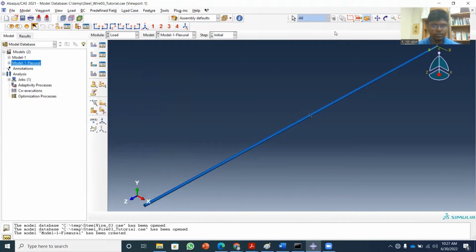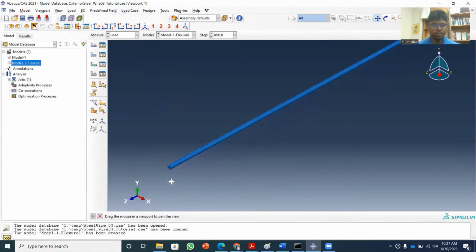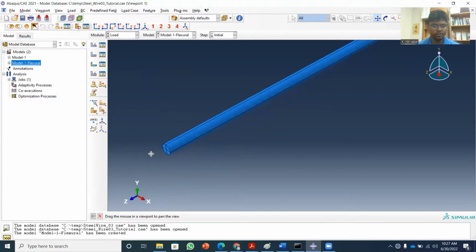While we were generating the longitudinal mode, we were applying our tone burst, or the load, on this surface, so the longitudinal, or in the axis of the pipe. Okay, but since we want to generate the shear mode or the flexural mode, which travels something like this way, we have to apply some force perpendicular to its longitudinal axis. So we have to apply some force in the y direction.